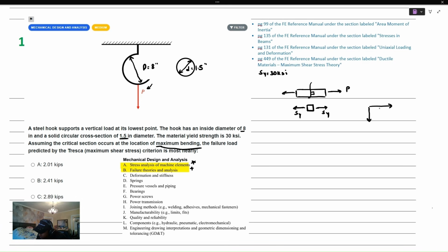what we could do is draw Mohr's circle and think about stress transformations. So we have a sigma in the x direction equal to the yield strength, so this would be S sub y here, and there's no shear. The axes here, if you didn't recall, are the normal stress and shear stress. If we plot the state of stress in the x direction, it's just equal to the yield strength, comma 0. So it just lies along that x-axis.